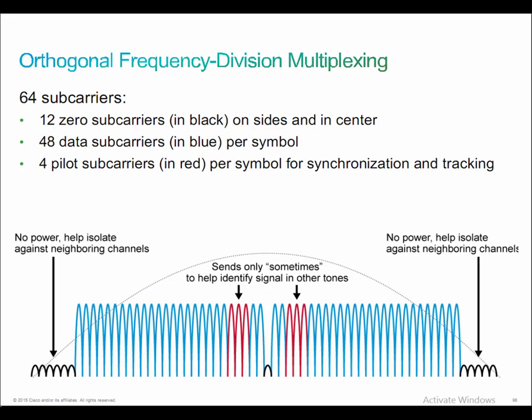Okay. The great advantage of this system is that if 48 channels carry the data, each channel can transmit slower than CCK channels, and the group of 48 will still achieve a higher throughput. For example, if each subcarrier is sending at 1 megabit per second, the total speed of 48 megs per second gets achieved because we're combining this information.